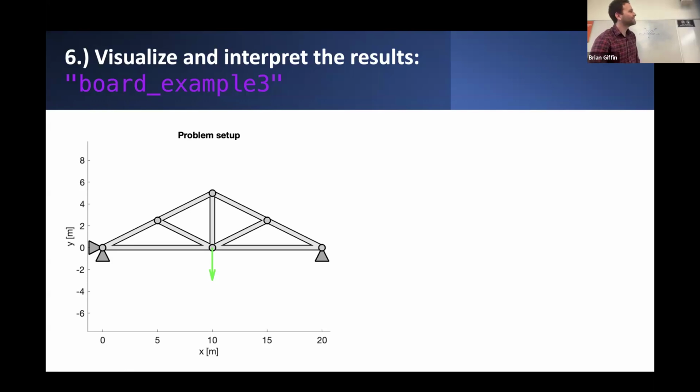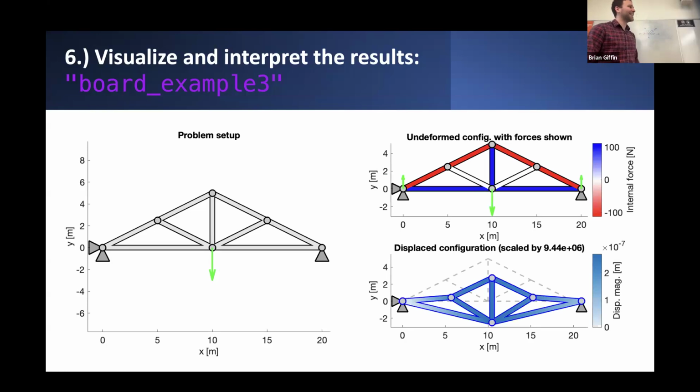And then this vertical member has to be... Compression. Well, think back to the previous example. It'll be a very similar rationalization for why this vertical member should be tension. So, vertical force pulling down, so this middle member has to pull back up.